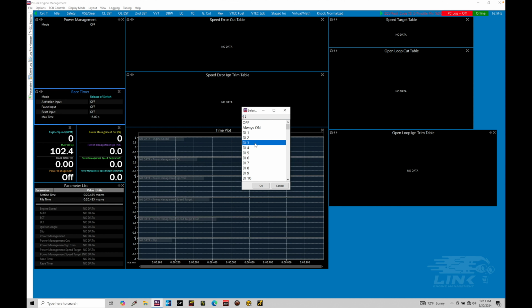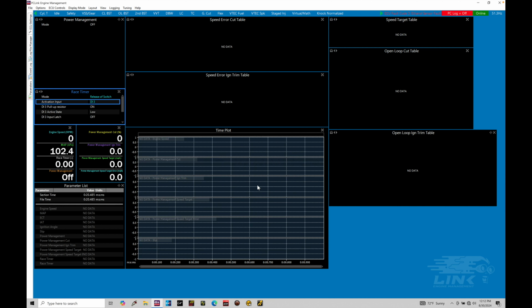The other leg of my button is going to go to my digital input 3 pin on my G5. So I'm going to be grounding the pin when I push the button. I have to note that, because not only do we have to know the input, but also the state here, which we're going to find in a second for assigning this. We can see here the pull-up resistor, if I'm sending a ground input to my pin, should be left on in the activation state low.